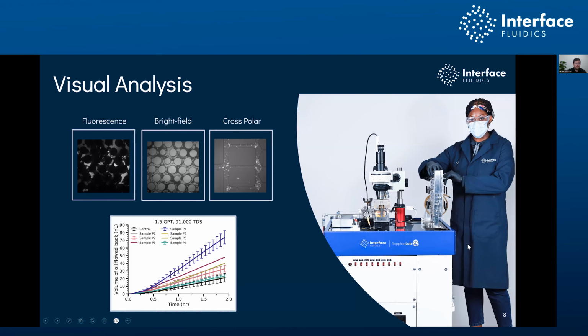I mentioned before visual analysis. So we use 3 types of imaging at Interface. The first is fluorescence. So whenever you see black and white images with bright white, that's the oil. So that allows us to understand where the oil is going, how it's moving, and how it's interacting. We use bright field imaging, the second picture there, to understand solids deposition, so things like asphaltenes, chemical instabilities, or other kinds of fouling that occur. And the third is using cross-polar microscopy, which allows us to visualize very clearly any crystals. So this is primarily used for wax and understanding how waxes deposit, how waxes form, and how they're changed by the chemistry that we're using.